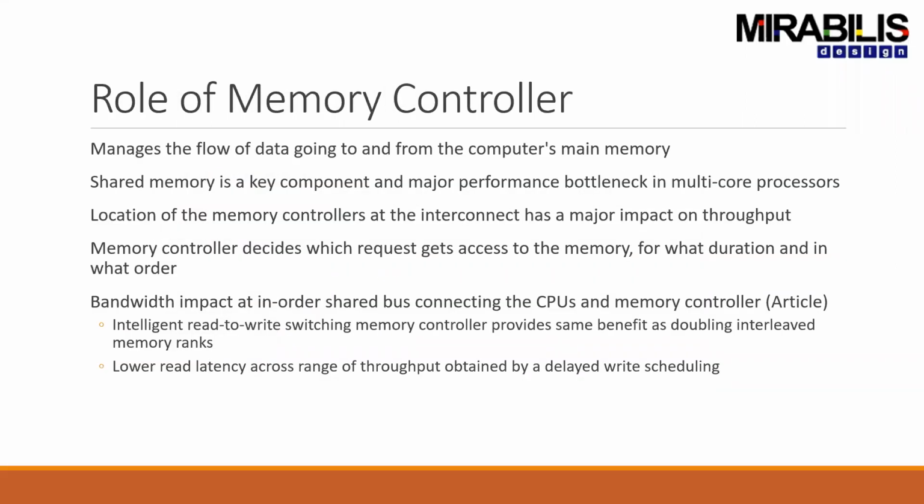Now, memory controller as a definition is a control unit that allows you to communicate between your masters, be it the processor core or an accelerator or a DMA for an interface, to the main memory. Memory is a key component in design. It's also shared, which means performance can be a major bottleneck. The location of the memory controller is probably one of the most complex elements of your topology design, be it on a NOC or on something like an AXI bus or even on a PCIe, depending on what type of design you're involved in.